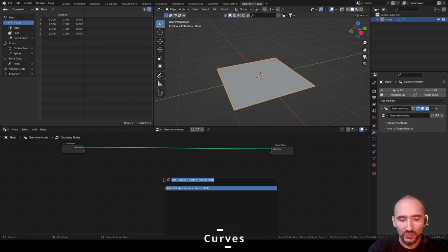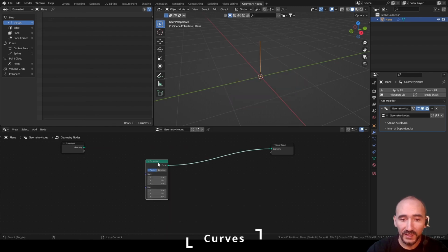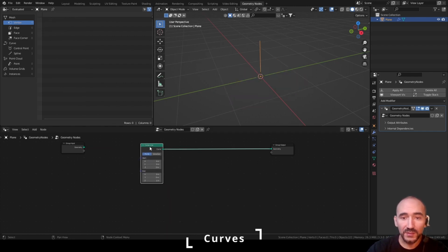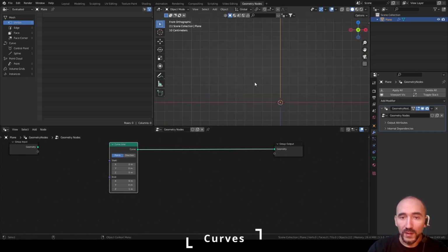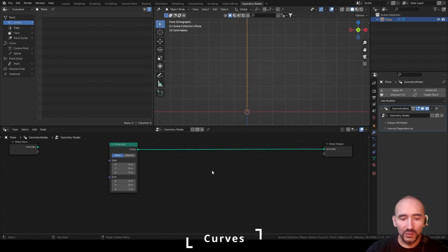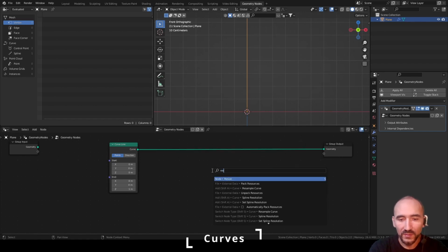So I have to create a single curved line, Shift Alt and click to isolate the selection. This is our line. Go with 1 to the front orthographic view, and we have to manipulate this line with a sine shape. So first of all, resample curve.